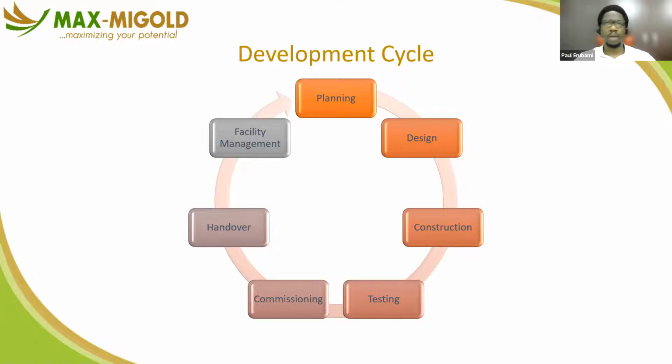This is where you look at the whole building and say, because it's all glazed all around, we've taken the measurements. It's still on paper, it's not built. We know how many square meters of glass. We can tell you that we want 15 millimeter thick thermal glass, double glazed for the paneling, and so on and so forth. They can come up with all those quantities and specifications, because this is translating the brief into reality. So the owner gets a sense of what is going to be bought, installed and built, and how much it is going to cost.